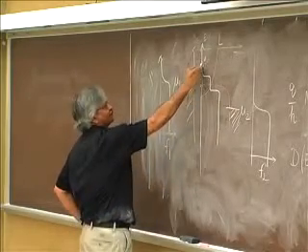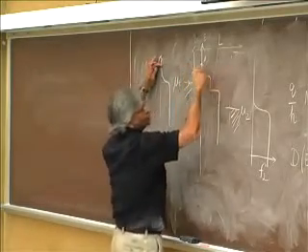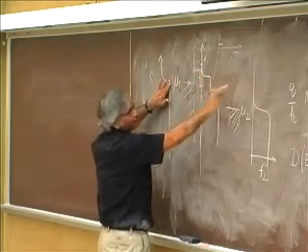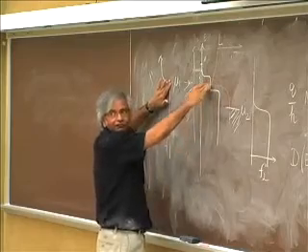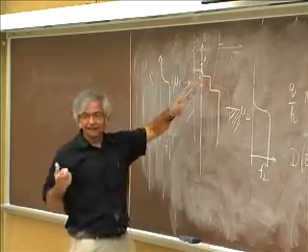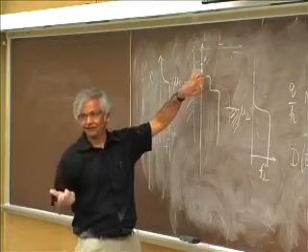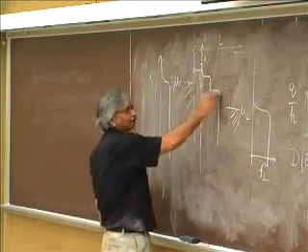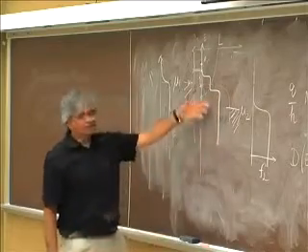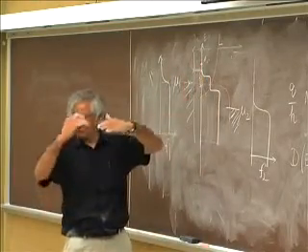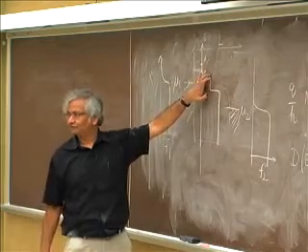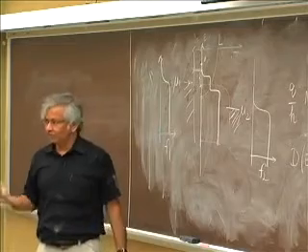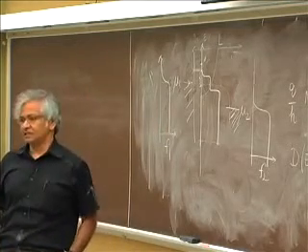Because in this region, this is 0, that is 0, so you get 0. In this region, this is 1, that is 0, so you get about half. Roughly, I mean, actually it is like half the states are well occupied, half the states are not. But if you looked at average occupation, it would have looked like that. And then at the other end, it's 1. And this, of course, doesn't quite look like a Fermi function, especially if you put enough voltage on it. And this is actually what the distribution would be if there were no inelastic processes inside your device.